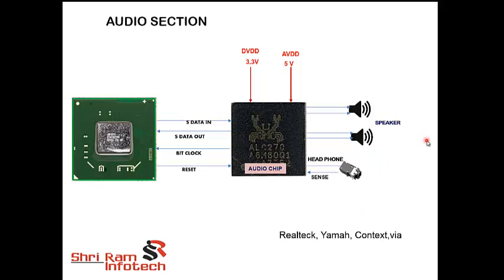If your drivers are perfect, then the next thing you have to check is the headphone. You have to connect headphones at this jack and check whether audio is coming out or not. If the audio is coming from this jack but not from the speaker, then you have to open the laptop. First you have to check this jack. Sometimes what happens is this jack gets faulty, the physical connections are not proper, and it's not sensing the headphone. At that time also your speaker will not give sound. So you have to check that first.